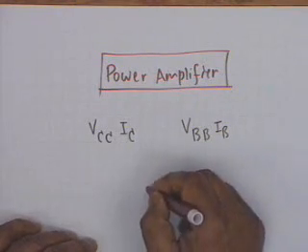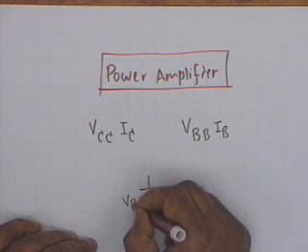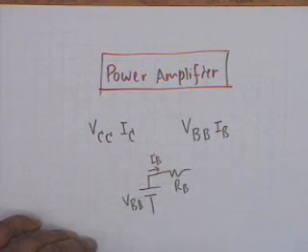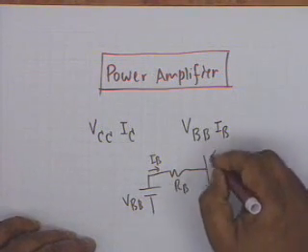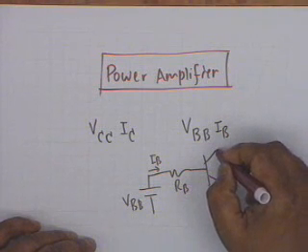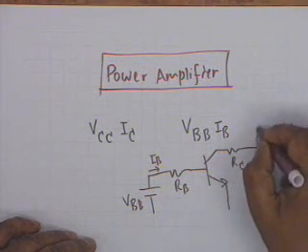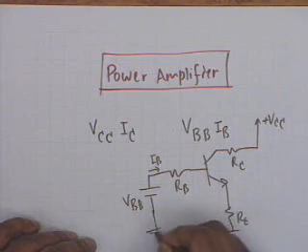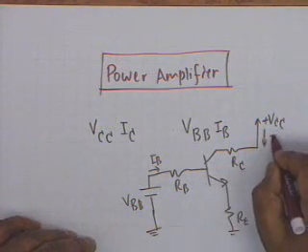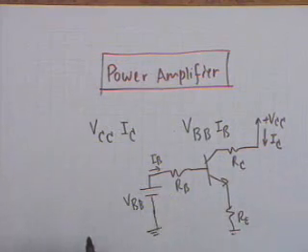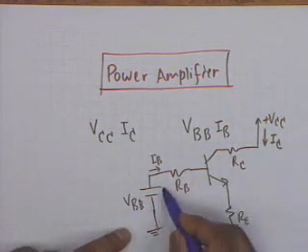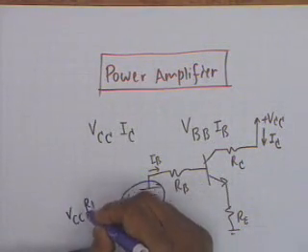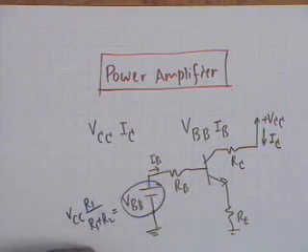You recall that the equivalent circuit is you have VBB, RB, and the current that is drawn is I sub B. Alright. This goes to the transistor, and the transistor has R sub C plus VCC. There may be an RE. This goes to ground, and this current is I sub C. There are two sources of power. One is VBB. What is VBB? It is derived from VCC. VBB is VCC R1 divided by R1 plus R2.